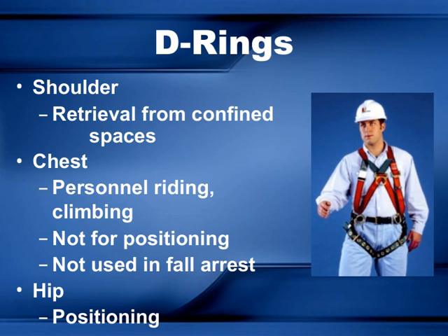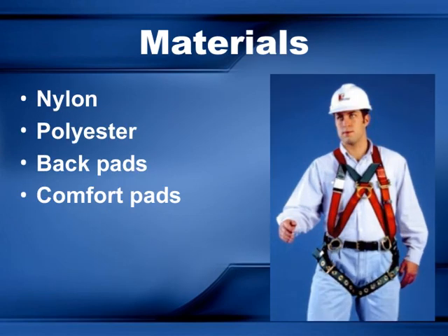Let's take a closer look at some of the materials we use, starting with nylon and polyester. These fabrics are essential because they provide durability and strength, which are crucial for the longevity of our products. Nylon, in particular, is known for its abrasion resistance and flexibility, making it ideal for areas that experience a lot of wear and tear. Polyester, on the other hand, offers excellent resistance to shrinking and stretching, ensuring that the product maintains its shape over time.